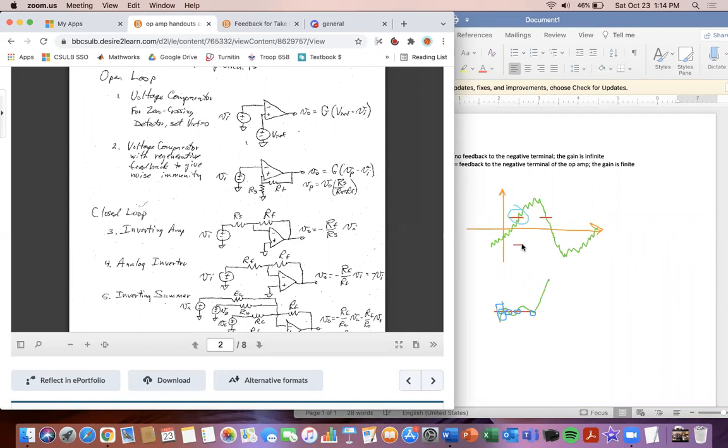So it would stop intersecting. And then when it intersects this once, then we would change it down here. And so we change our reference point. And so that's what this voltage comparator basically does, it gives noise immunity by changing the reference. And so once it intersects once, then it changes that reference position.